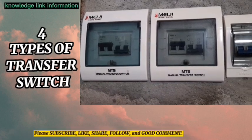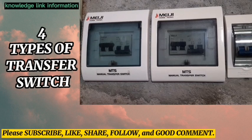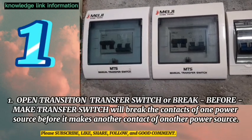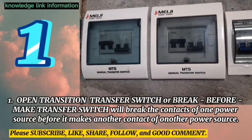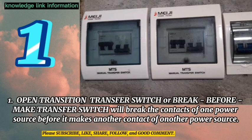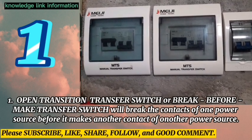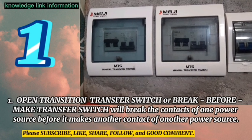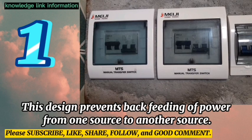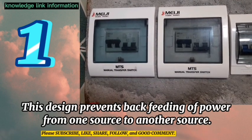4 types of transfer switch. Number 1. Open transition transfer switch or break before make transfer switch will break the contacts of one power source before it makes another contacts of another power source. This design prevents backfeeding of power from one source to another source.